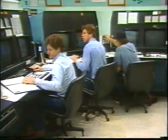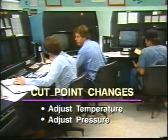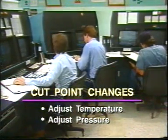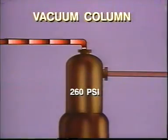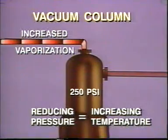Adjusting the heat balance so that a column will make more or less of a particular product is called changing the cut point. Although cut point changes are frequently made by changing the column temperature profile, they can also be made by adjusting the column pressure. Recall how pressure affects the boiling point of a liquid. In a vacuum column, for example, the pressure is reduced so that more vaporization will occur at moderate temperatures. So reducing the pressure has the same effect as increasing temperature.